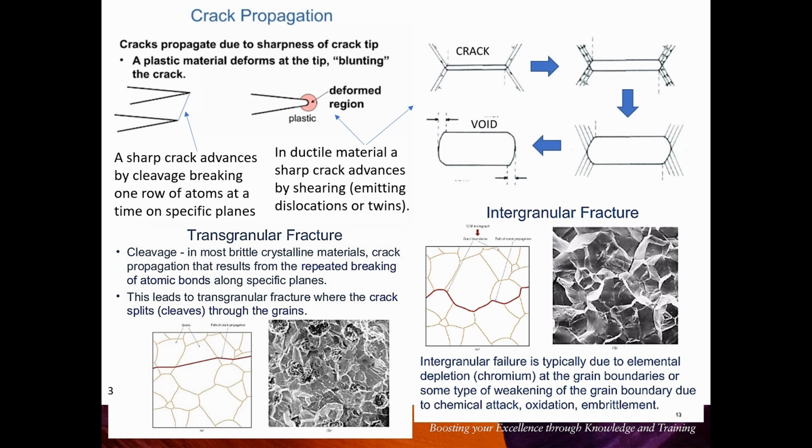That can happen at an inhomogeneity, because you have a hard precipitate and it doesn't deform the same as the matrix, and eventually incompatibility stresses build up, and you get some stress sufficiently high at a small enough scale that you get, in essence, the separation, the cleavage on a microscopic scale, and a crack being formed.